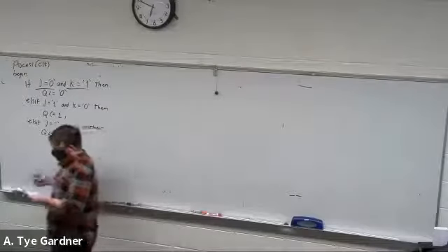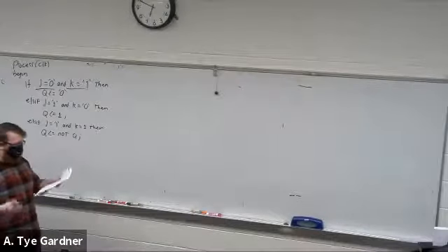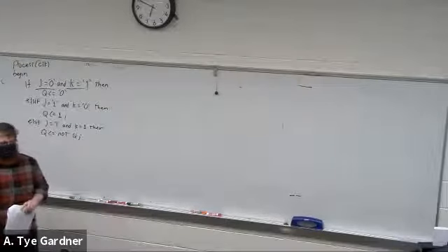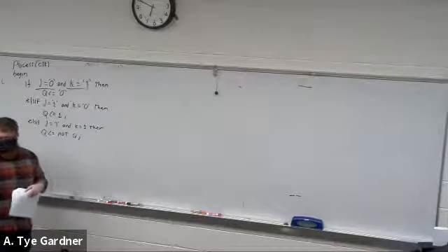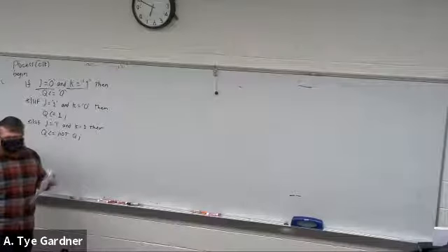So let's go ahead and use T flip-flops to build a counter, actually. Let's go the other way, which if you think about it, clock dividers are really just counters that just flip a bit when they're done counting to some number, right? 2 or 4 or whatever.